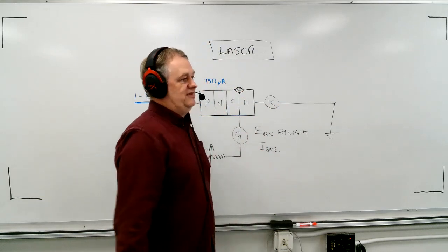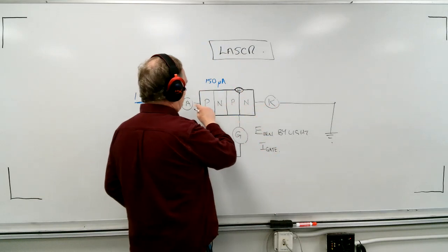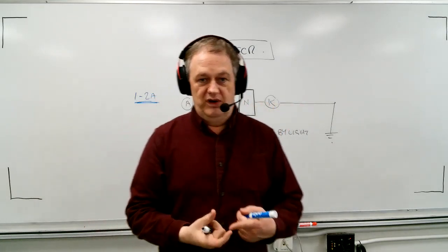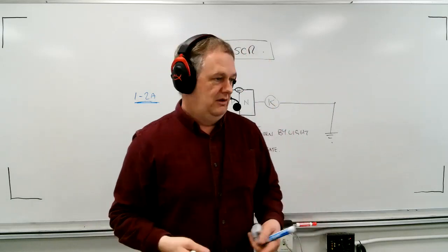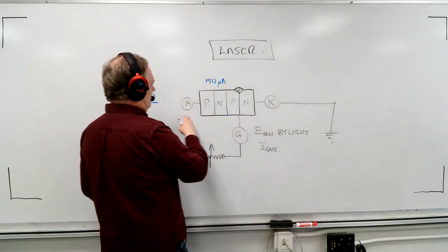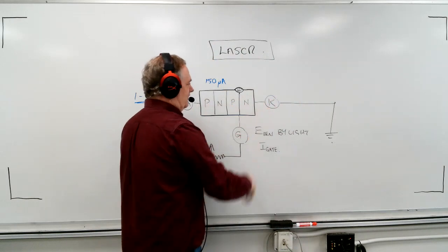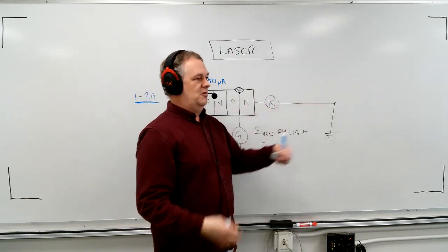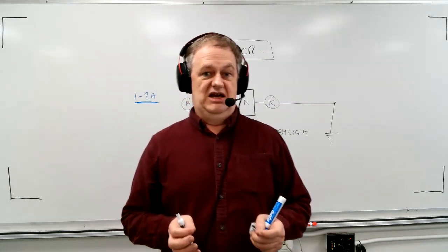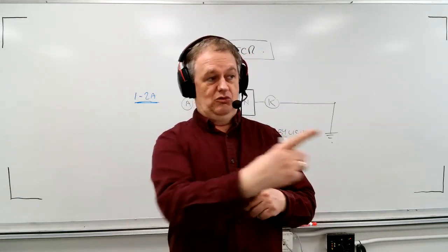So if you had a 15 amp lighting circuit, you can't run it through the SCR. So what you have to do is this current would actually be operating just the coil of a small relay, and then that relay might have 20 or 30 amp rated contacts, okay? So just imagine this. Imagine it's dark. This is off. This is not conducting. So you would want the output of this probably connected to a relay where if it's de-energized, it would have a normally closed contact that your lighting circuit would run through.